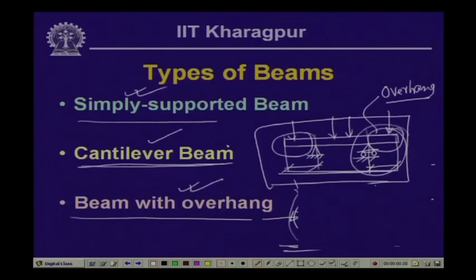So, henceforth whenever we mean that a simply supported beam is loaded with transverse load, it means that the beam is supported on a hinge support at one end and the roller support at the other. Or if we say that a cantilever beam is loaded with such and such loading, it means that one end of the beam is on a fixed support and the other end is free, and when there is a fixed support, it is expected that there will be three unknown reactive forces which are to be evaluated using equations of statics.